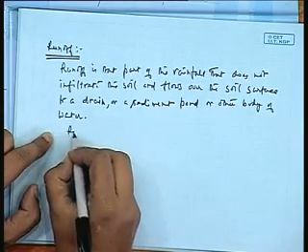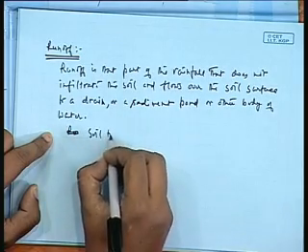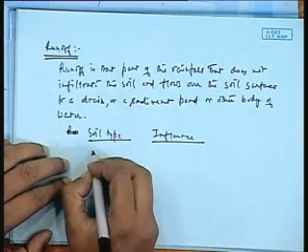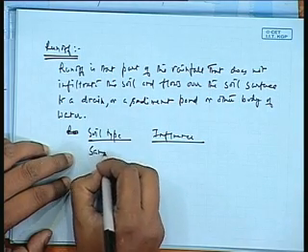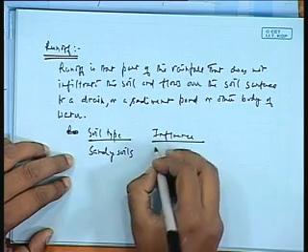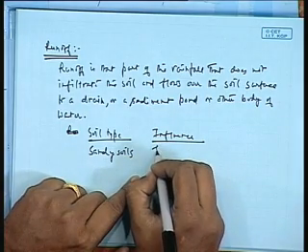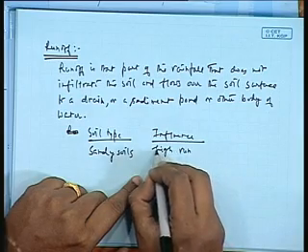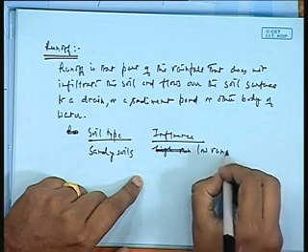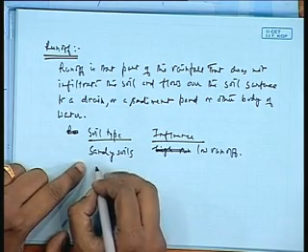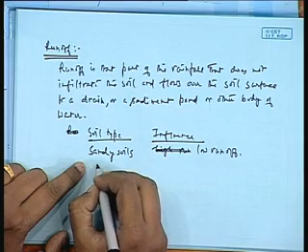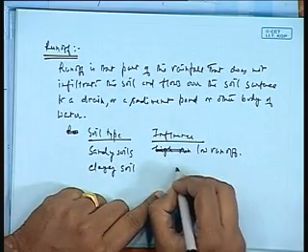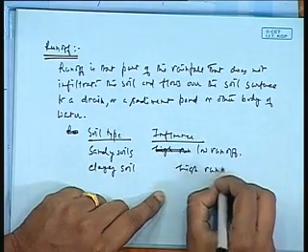Influence: soil type. If we just see the soil type, sandy soils have high infiltration, so low runoff. Clay soils have high runoff.